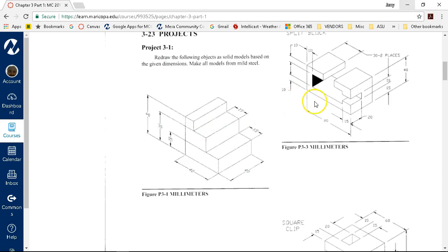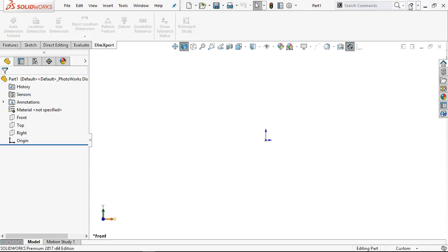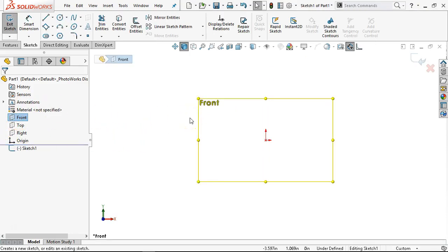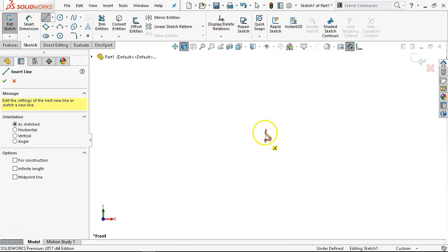And then the multiple features, if you haven't started, you will now. If you haven't done separate features as cut extrudes or separate features as fillets, this is going to force you down that path with the strategy. All right, so 40, 30, 15. I was looking at this thinking, I really want to make this more complicated than it's worth. So I'm going to introduce global variables. And it's another one of those handy tools.